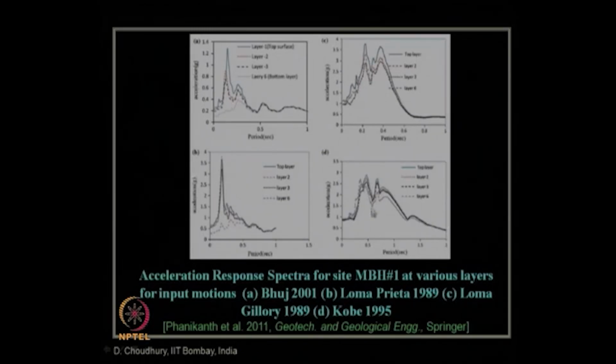So, that means it is not that the same structure will be subjected to the same amount of damage irrespective of ground motion, but it will be subjected to damage depending on your input motion. That is, Bhuj motion will cause maximum damage to a structure having a period of 0.2 second, whereas Kobe motion, if it comes to Mumbai at that site, will damage a structure having a period of 0.5 seconds. Is it clear how we are using these things for further design?